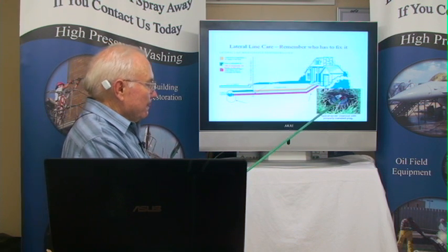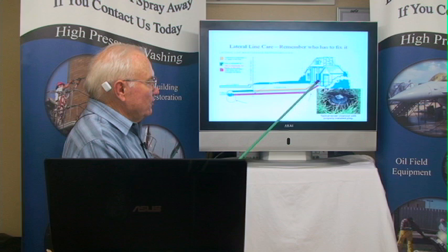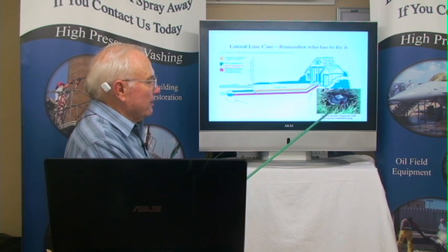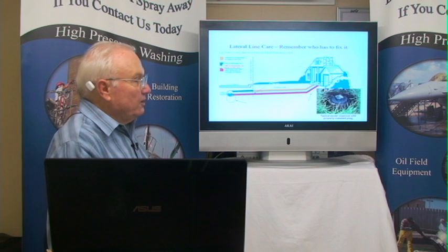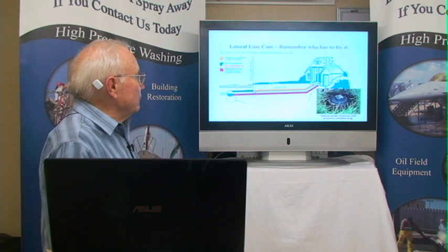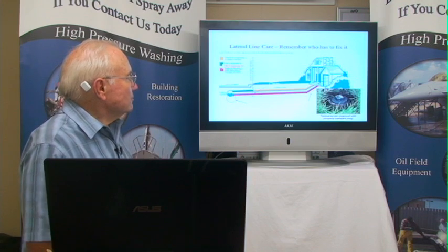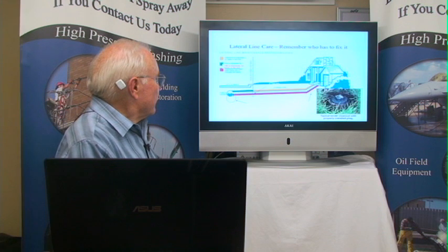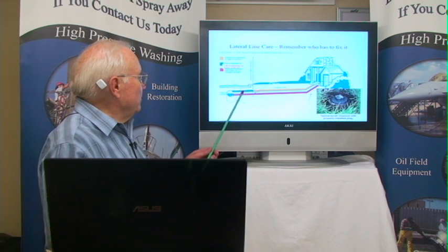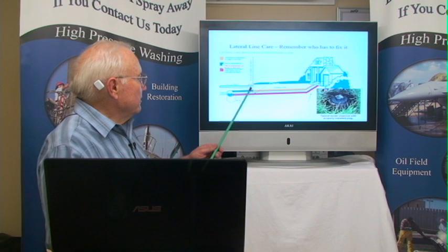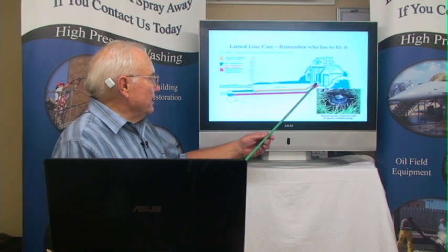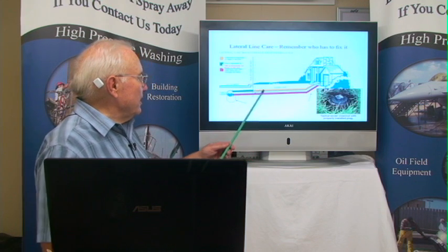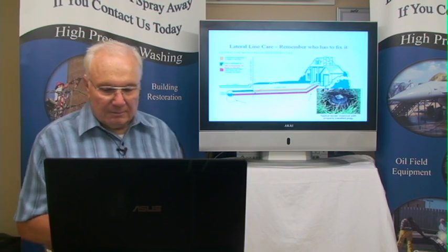Now then, it's legal, since it's on private property, for the contractor to unscrew that and discharge into it with the property owner's permission. So you can't get into this area. You have to enter the sanitary sewer system on private property, not public property.